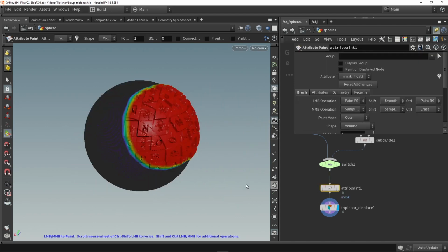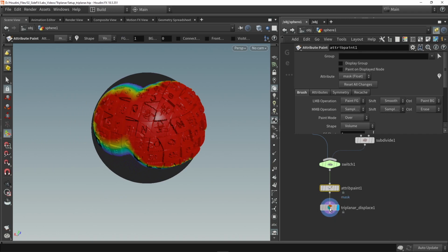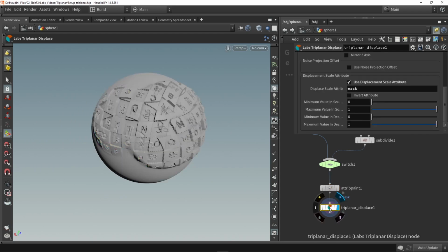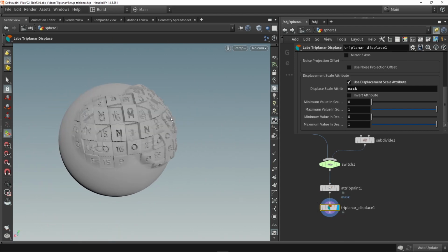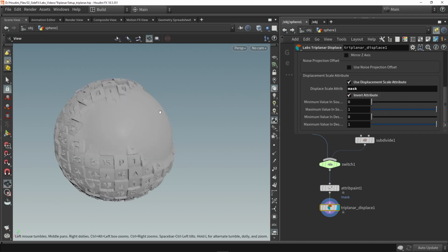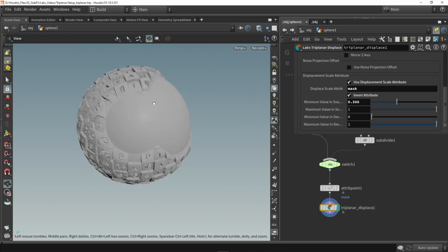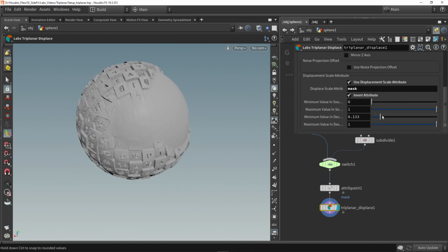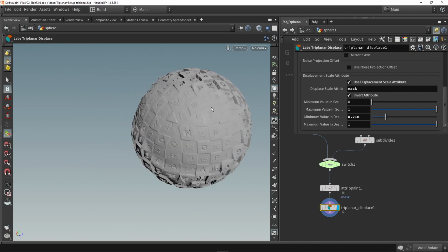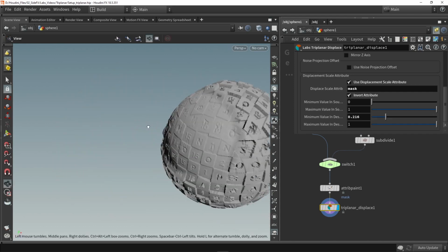So you can either paint the result, like I did, and if I want some parts here as well, we can paint that. Or we can procedurally generate attribute noises or calculate areas where I want displacement. So we can control the displacement with attributes, which can be very useful. You can also invert this, and we can play around with the range more. We can play with the transition, or we can steadily blend some of the shape in there still.